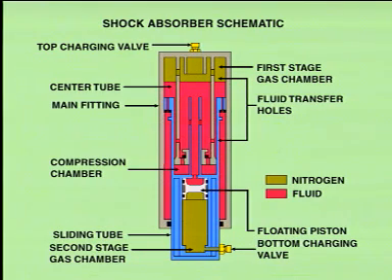Warning! Do not put compressed gas in contact with your skin. The gas can go through the skin and cause bubbles in the blood. This could cause death. Make sure that the area around the aircraft is clear of persons and equipment. When you pressurize or depressurize the shock absorber, with the aircraft weight on the ground, the aircraft will move. Caution! Always add nitrogen slowly when you pressurize the shock absorber. If you add nitrogen too quickly, the temperature will increase and have an effect on the shock absorber pressure.